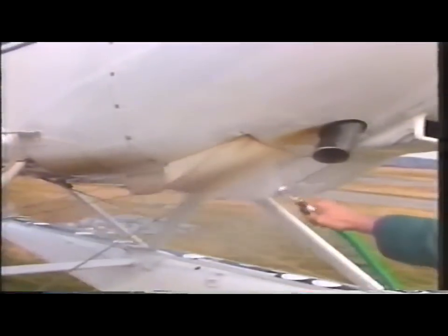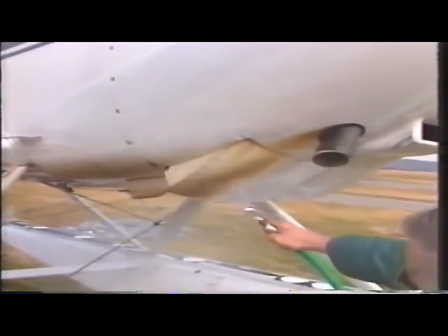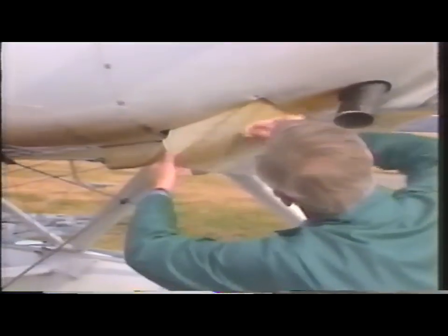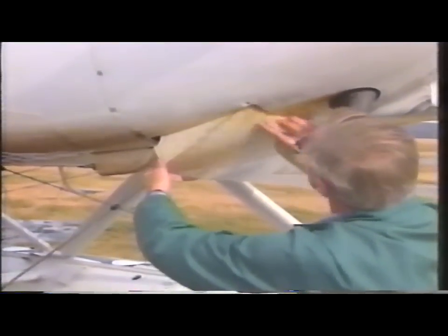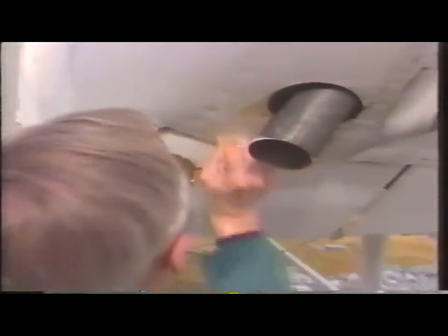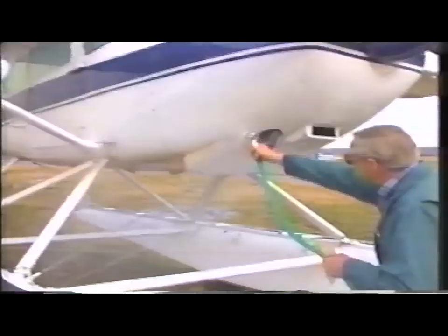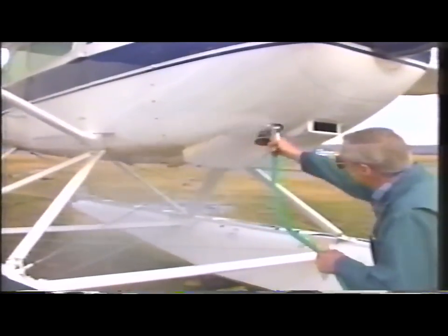Because both jet and reciprocating engine exhaust gas deposits are very corrosive, exhaust trail areas should be cleaned daily. Also check for paint blisters and chipped or missing paint. Inspection and maintenance of exhaust trail areas should include attention to gaps, seams, hinges, and fairings which are located near the exhaust path. You should remove fairings and access plates whenever possible.